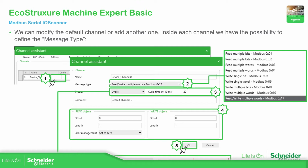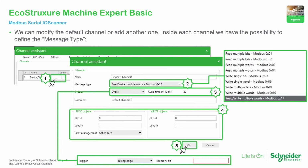So first, we need to define the type of message that we are going to use to communicate with the device, or in which area of the slave the information is located. So for example, if you want to read a percentage MW, you probably need to use this one, read multiple words, or write multiple words.